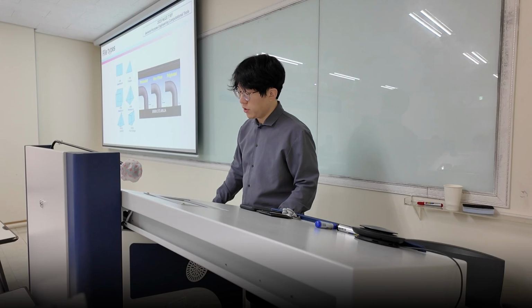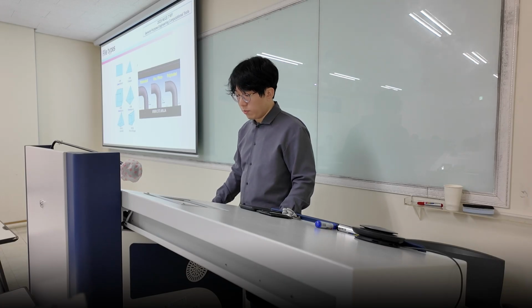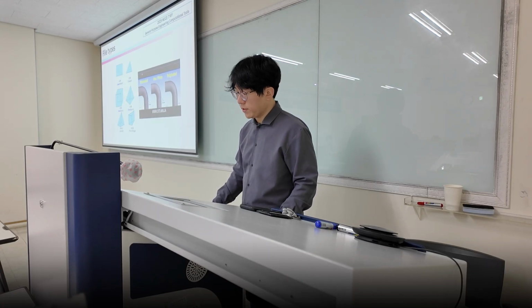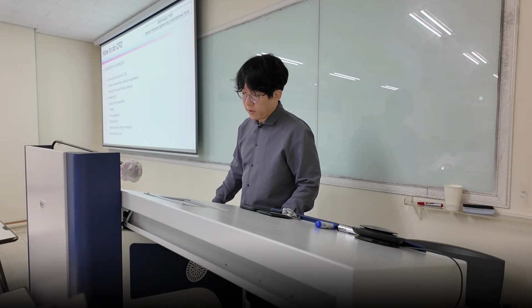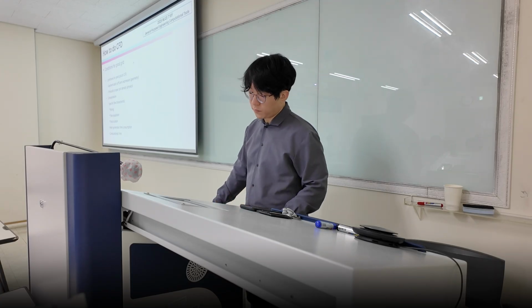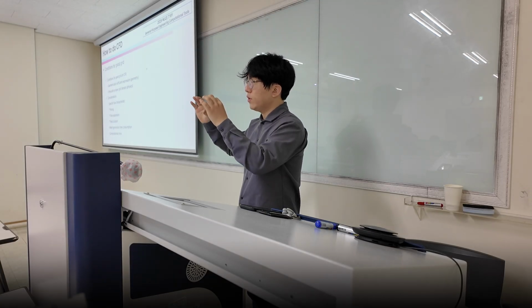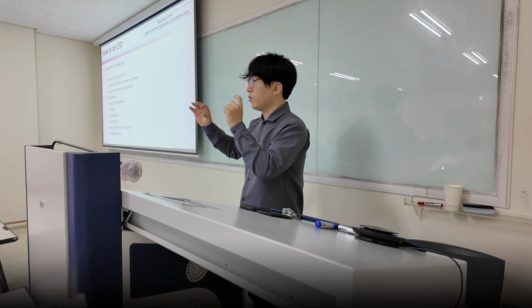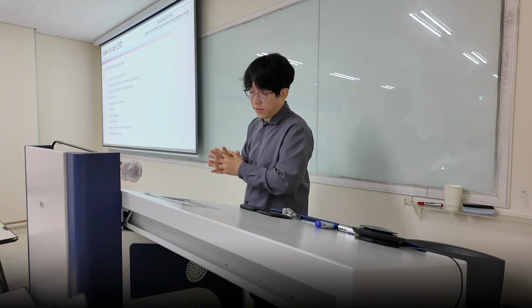There are different types of mesh. These are cells, and then if the cells are all combined, we call them mesh. Usually we often use tetrahedral, so remember this shape. And we're gonna also check the grid conditions. Make sure the grid conditions cover the flow characteristics. So if there's wall behavior, you have to have a finer resolution around the wall, and depending on the turbulence model you use, if it's either K epsilon or K omega, you have to make sure you have the right wall function as well.